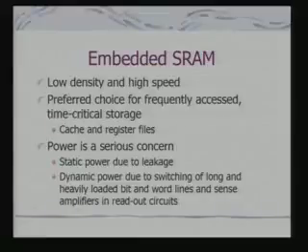Then there will be power consumption, what we call dynamic power consumption, due to switching of long and heavily loaded bit and word lines, because these bit and word lines are connected from cell to cell. Obviously, I shall need current to drive these bit and word lines to provide me the correct data. So there will be dynamic power consumption. That current will be driven into those lines when I am actually selecting or reading a word from the memory or writing a word into the memory.